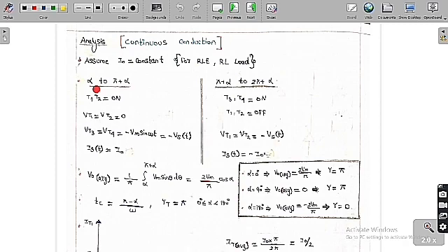And I have already told you that from alpha to pi plus alpha, T1 and T2 are on. Whenever T1 and T2 are on, the voltage across T1 and T2 is equal to 0. If you apply KVL across T3 and T4, we get minus of Vs of t, which is minus Vm sin omega t. This is the expression from alpha to pi plus alpha. Now if you apply KCL, the source current is equal to the load current from alpha to pi plus alpha.